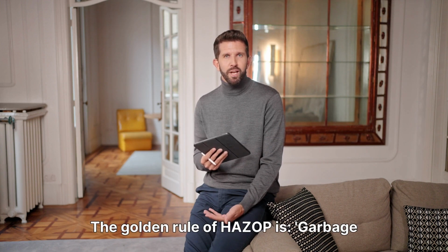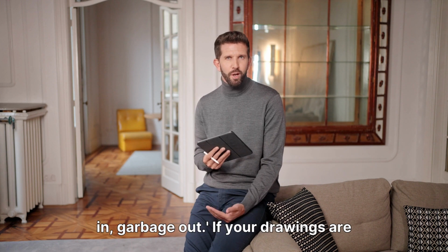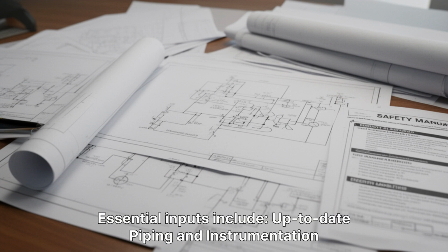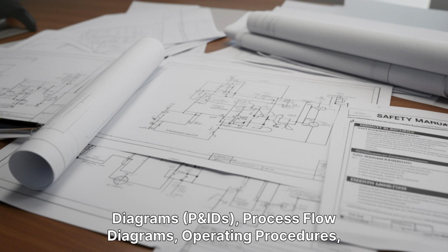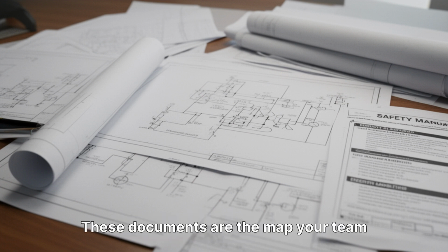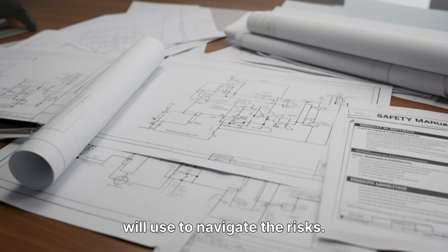The golden rule of HAZOP is garbage in, garbage out. If your drawings are outdated, your study will be worthless. You cannot analyze what you cannot see. Essential inputs include up-to-date piping and instrumentation diagrams, P&IDs, process flow diagrams, operating procedures, and material safety data sheets. These documents are the map your team will use to navigate the risks.